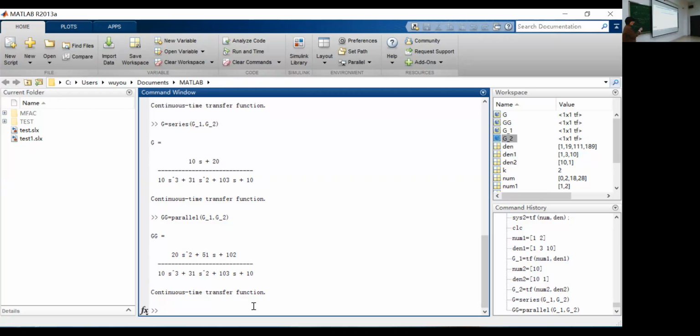Then how to get the transfer function of negative feedback? You should first identify it is not in parallel, it's a feedback. What is the difference between parallel and feedback? Parallel forms are connected in the same direction. But feedback is one direction to output, another direction from output back to input. So you cannot just do minus here. The directions are not the same.